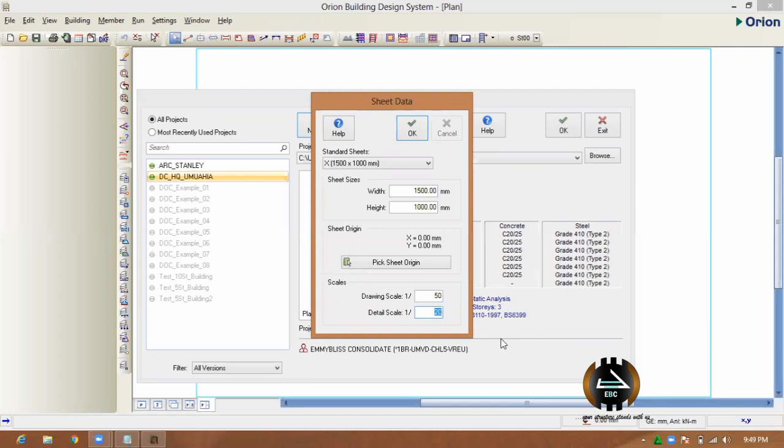It is the same dimension, but the scale is different. Do you get? So now this is just about the scale of the drawing. So your detail is to scale 1:20. So I can take my details to scale 1:15 to make it bigger. Now my drawing scale, I can bring it down to scale 1:45.